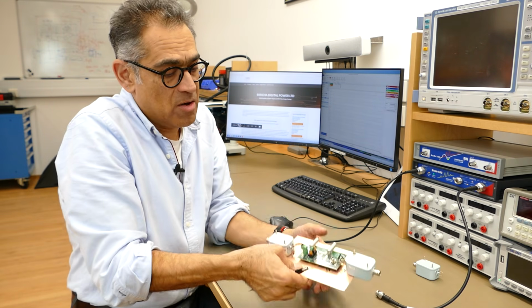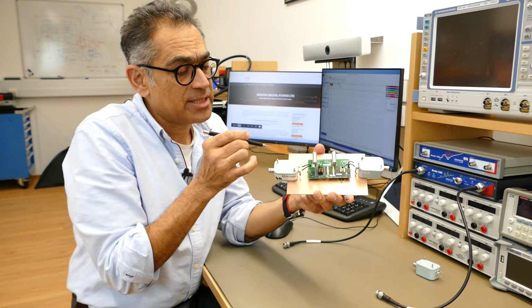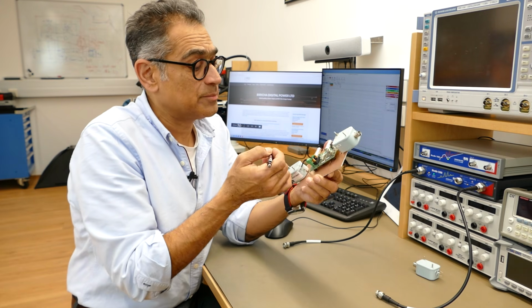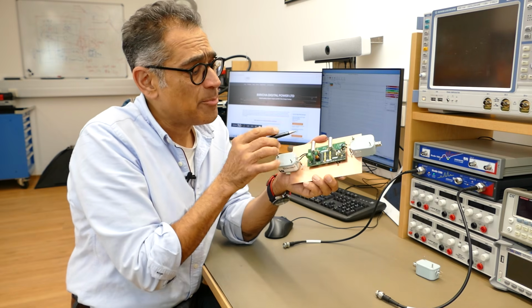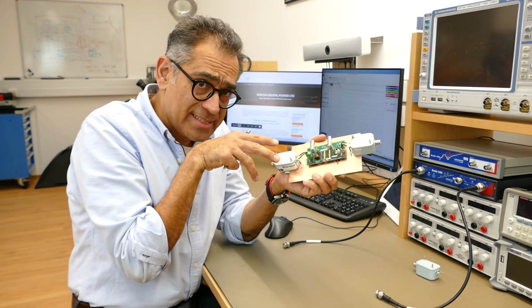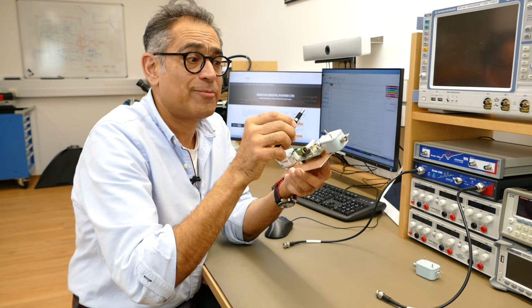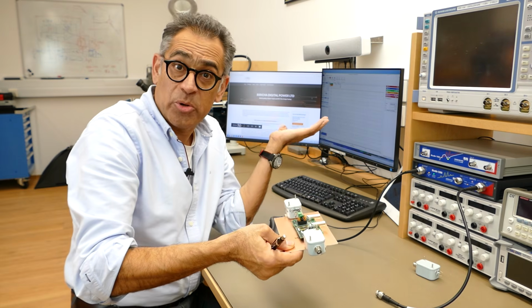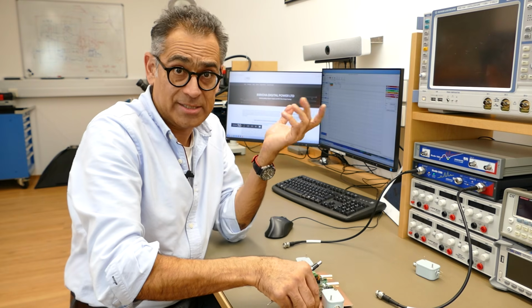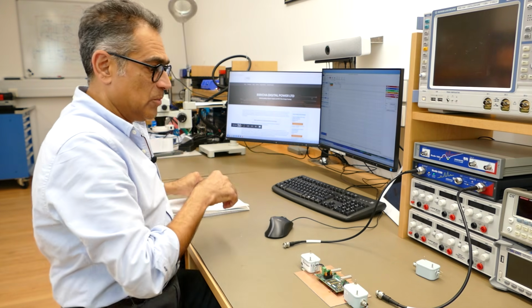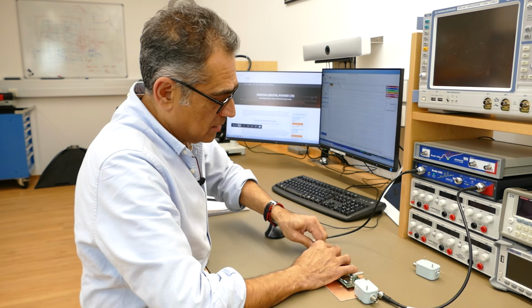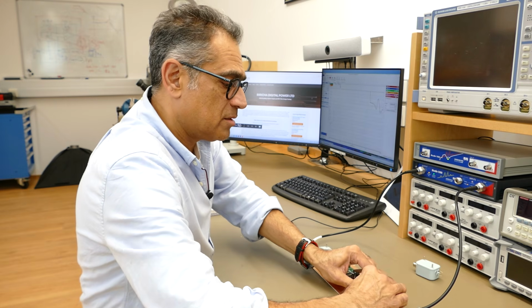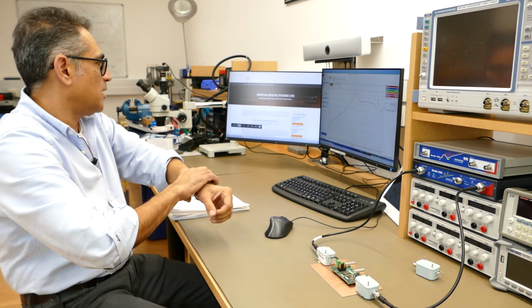So what is happening now is that I am injecting a signal through here with my Bode 500, then that is split with a center tap, and a differential mode signal is being sent through here, and then I'm measuring what is coming out of this identical transformer on the output, and then of course the Bode analyzer suite will automatically plot the insertion loss for me. So let me connect it up and we'll see what it looks like. So that is the injected signal. That is my signal that's coming out, and there we go.